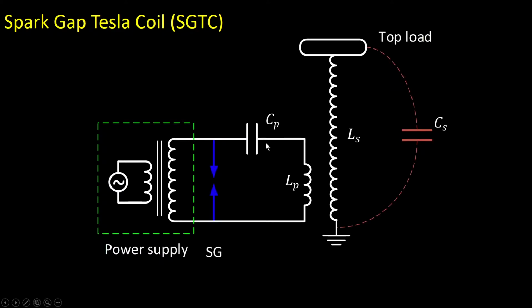When the voltage of the capacitor reaches a certain value above the breakdown strength of this spark gap, basically here we will have a spark. So if there is a spark here, now we will have a loop in this smaller part. Basically, all the voltage of the capacitor will drop over this arc resistance together with this primary coil. So thousands of volts would drop over this circuitry. And so hundreds of amps, maybe thousands of amps, would flow through this loop for a very brief moment of time, several microseconds. So a high current passing through this primary coil will create a magnetic field.